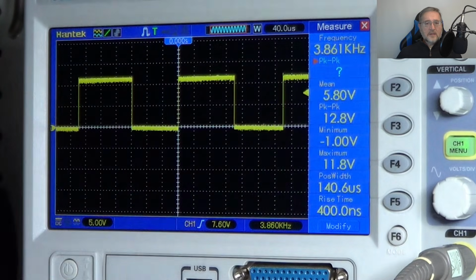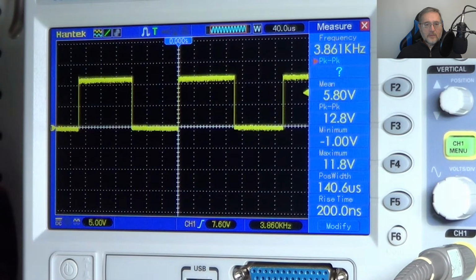But this is within the tolerances of the voltmeter of the power supply, which has not the same precision as the oscilloscope. Now, you might think that I could use an actual digital multimeter to measure the values. However, the multimeter will not show me the peak value that I want, but only the RMS value, which in this case will be around 6 volts.